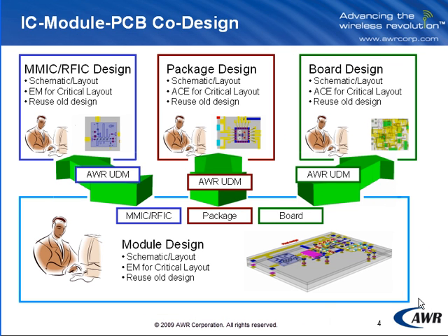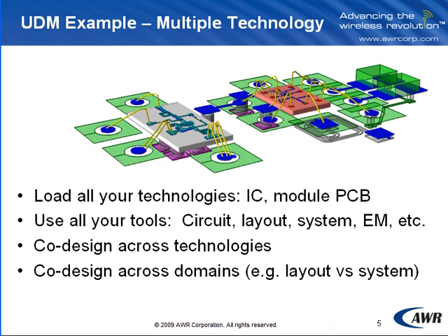This allows us to really have a very flexible flow where we can either individually design MMIC or RFICs, packages, or boards, but then we can also think about integrating them and co-designing them together as their constituent parts, or as black boxes where we really don't go inside and touch them, but we have that flexibility to load the entire module in all its complexity into the design environment and be able to make trade-offs at whatever level necessary.